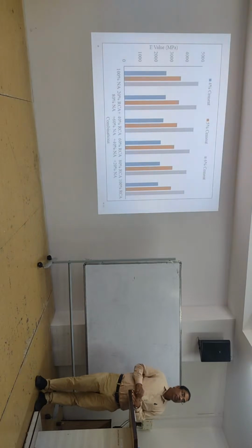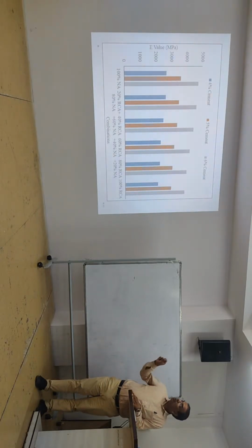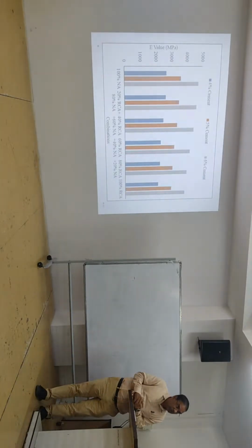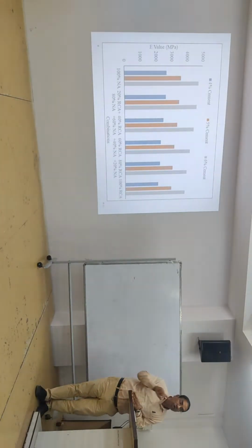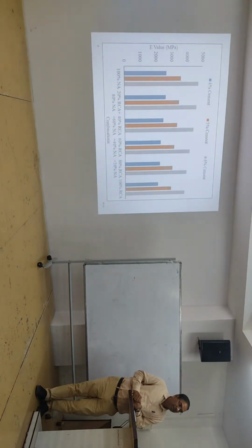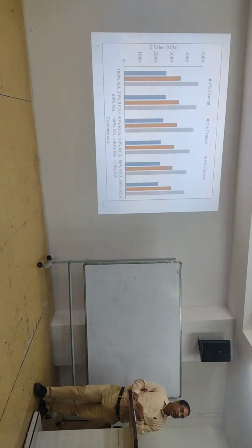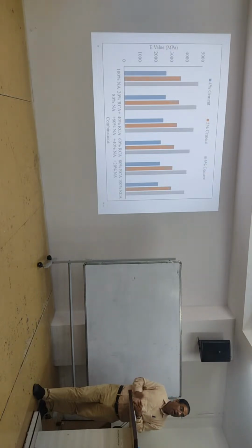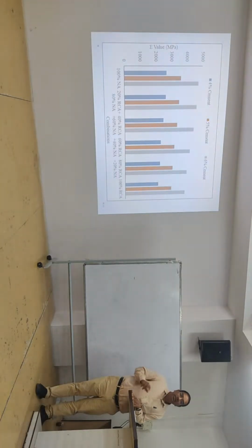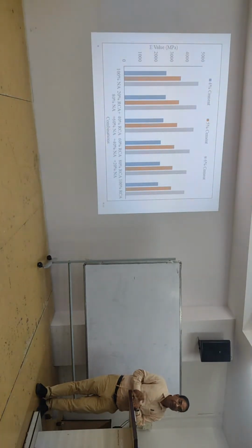So this is a new type of approach. If the sub base and base are improved more, we have more strength, so the top thickness will be decreased. Geotextile and geogrid are nowadays used by a lot of people, minimizing the top layer of bitumen. Bitumen is very costly. Suppose the bitumen thickness is 200 mm. If we improve the modulus up to 2000, then the thickness will become half, so only 100 mm thickness of the bituminous layer is required. National highways are all using this, decreasing their bituminous layer to 100 mm.